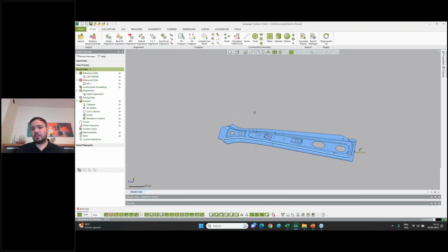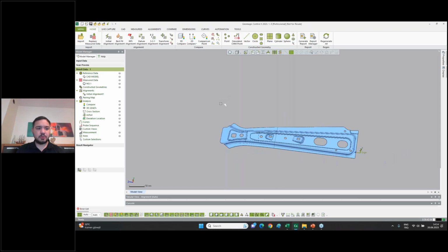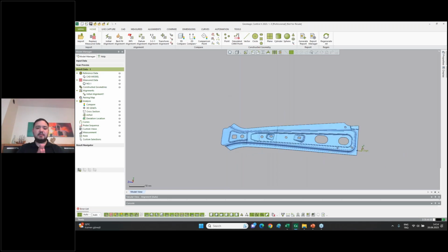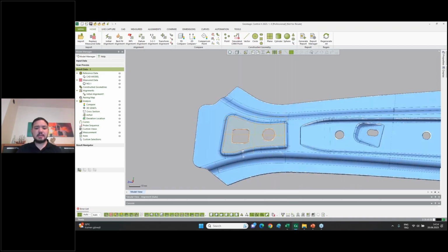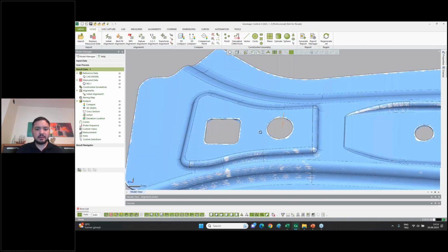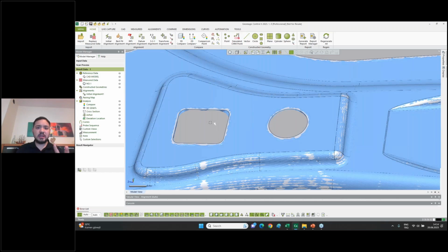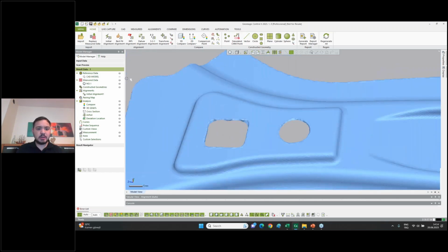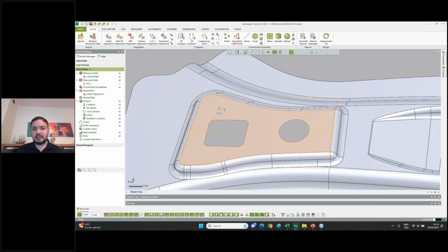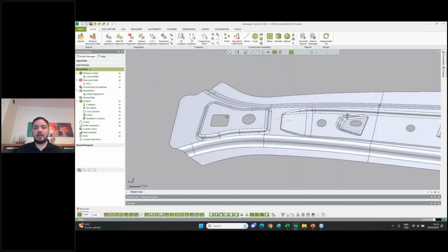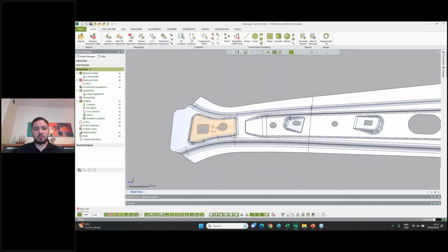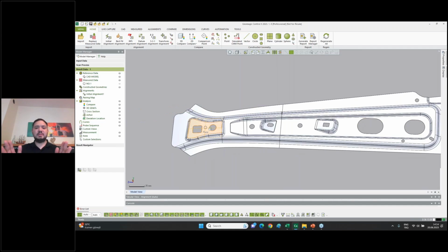And the program easily recognizes the position of the CAD model and the laser scanning, and it merges them together. So after this alignment, Control X can now find the measured and nominal volumes in the CAD model. As you can see, I just move my cursor to the plane, and it is also picked as a measured one. So I don't need to create any geometries to measure the opposite component. It just automatically pairs the measured parts.